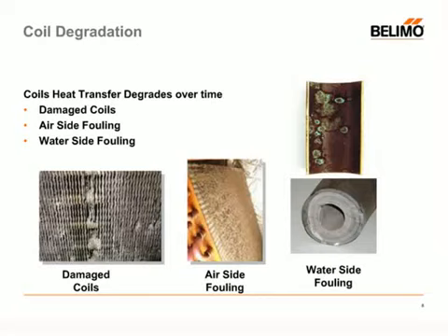For those of you that have forced hot air in your homes, we have that filter that's supposed to be changed once a month. And I can assure you that in my house, it's not changed once a month. It's lax, and the same thing happens in commercial situations. So what ends up happening is this layer of dust acts like an insulator, like a sweater, and it impedes heat transfer across the coil, reducing the output of the coil.